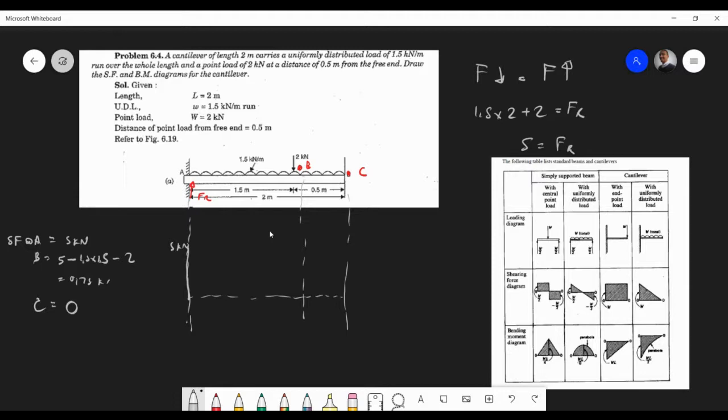Moments will do that. This is shear force. All right. So now at B, what's going to happen here? Across the whole thing, we're going to go 5 and we're going to dip down. Then over here, we're going to be pushed down again. And then over here, we're going to go down like that. So it's 5, 0.5, and then 0.